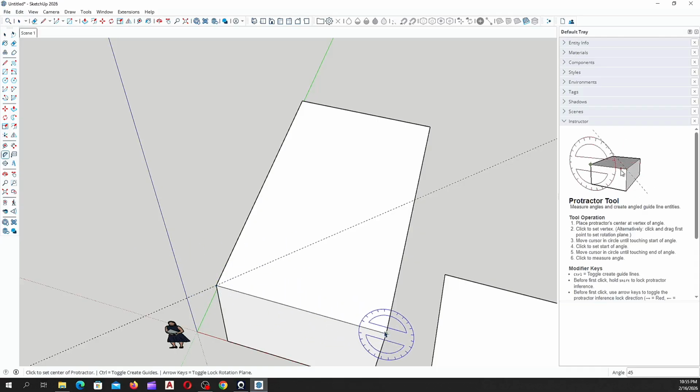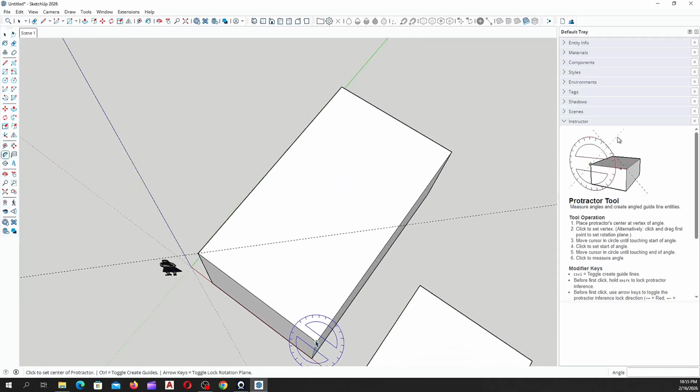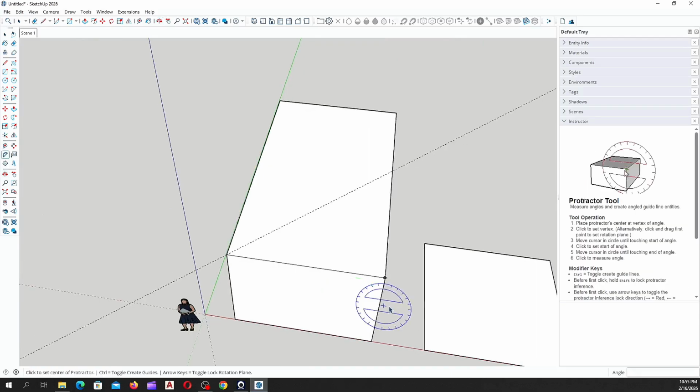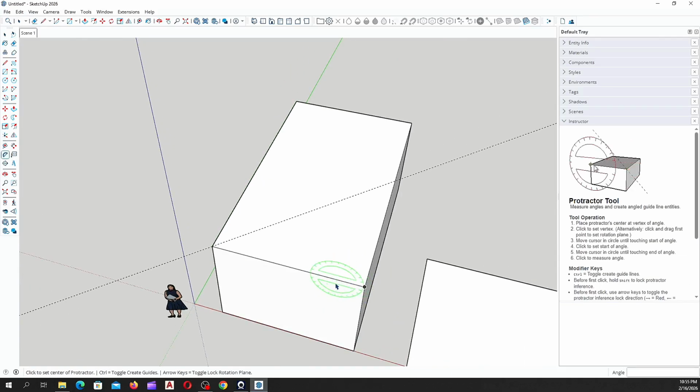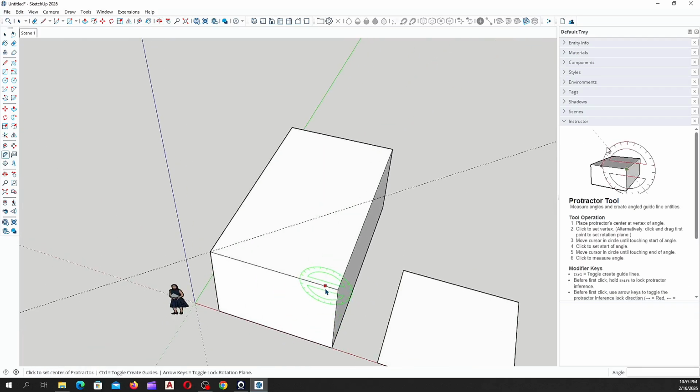Enter. Then I can come to this point and pick the same. You see, if I'm finding it difficult to snap at the top of this object, I can press my up arrow. You see, automatically it locks. Wheresoever I move, it always shows blue. And I tap it again, it deactivates. You see, coming here, green, blue. Coming to this portion is showing red. So whatsoever axis you drop your tool on, it always mimics the color. It shows the color of the axis.